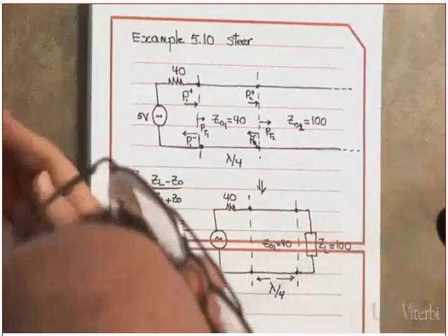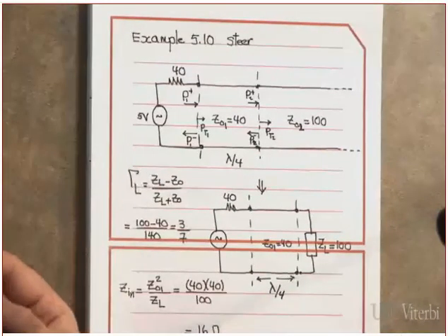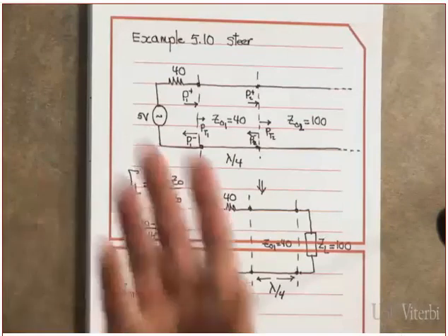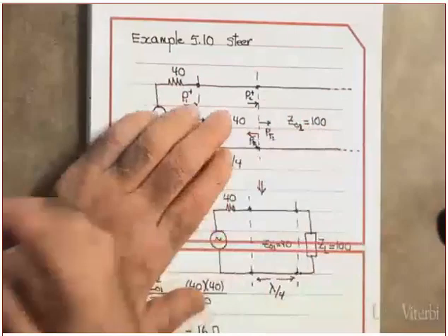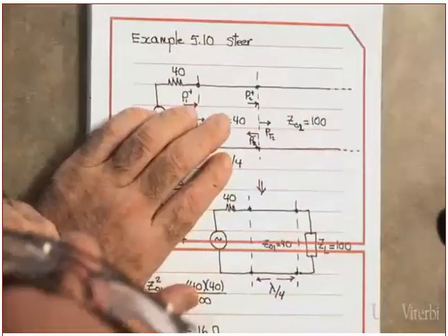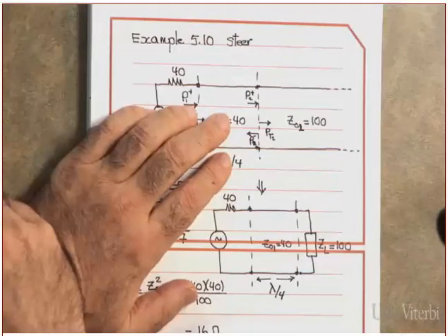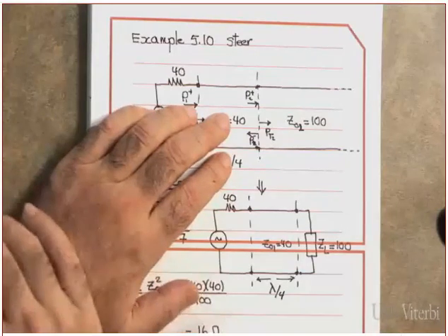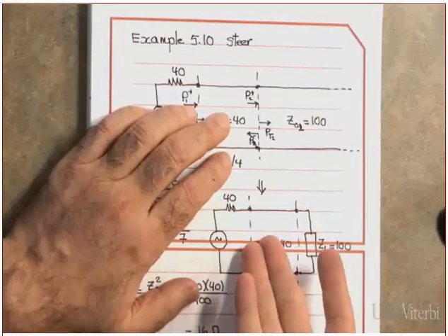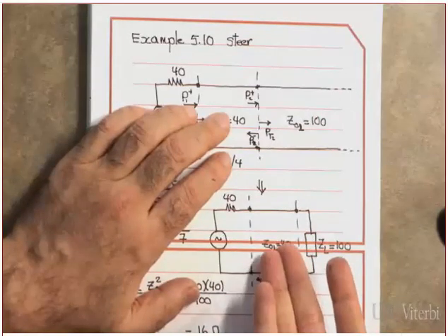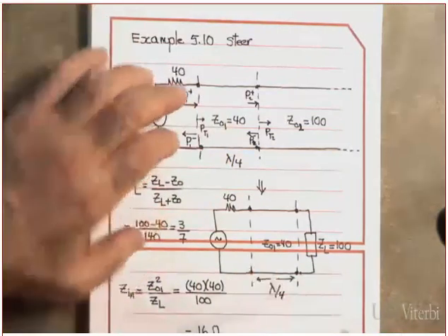So if the question in the midterm gives you that the line is of infinite length, which is something not practical. And in practice, do we have infinite length? We don't have infinite length. I did it just on a piece of paper. If the question tells you that the line is of infinite length, it means that you can replace the line by its characteristic impedance. So what did I do? I replaced it by ZL 100. And what did I discover? I discover there is a mismatch at the load. Did you get this or not? There is a mismatch at the load.